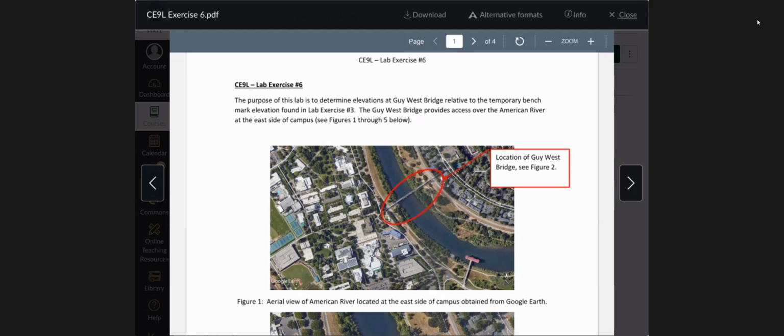You won't be going in a loop. You're just going to be going basically in a straight line across the bridge. So there are no correction calcs to make because we haven't closed back on our original known elevation. So you're just calculating a series of elevations based on several foresights that you're going to be measuring as you go across the bridge, okay?